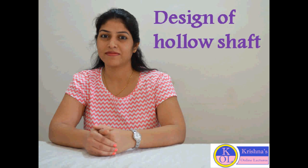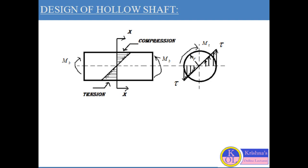Hello students, today I am going to discuss the design of a hollow shaft. We generally observe that the bending stresses and the torsional stresses are zero or negligibly small at the center of the shaft. So we can say that when the radius of the shaft increases, the resisting stress due to external bending and torsional moment also increases. So in resisting the moment, generally the outer fibers of the shaft are more effective.